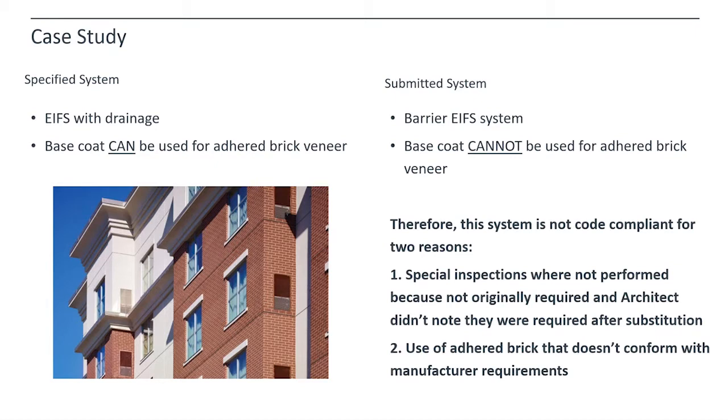The first reason is that in the IBC, I'm thinking the recent 2012, 2015, you can have a barrier EIFS system here in the US, but it has to undergo special inspections in order to be allowed. So when they switched unknowingly to a barrier system, nothing was inspected, and therefore they didn't comply with the code requirements.